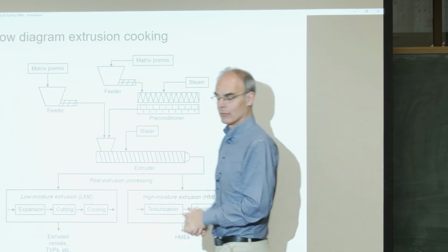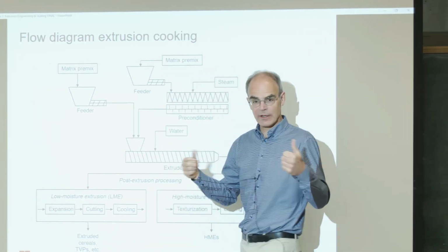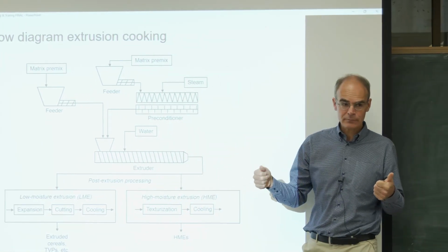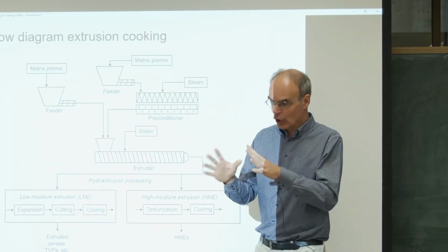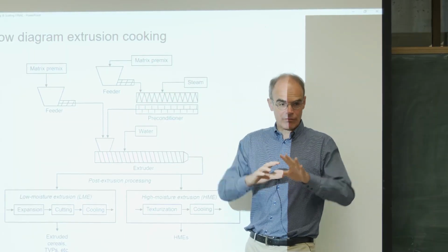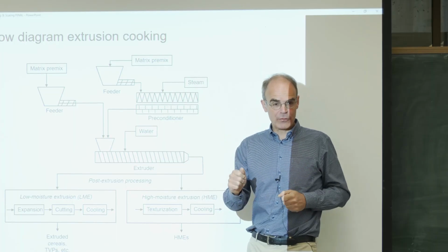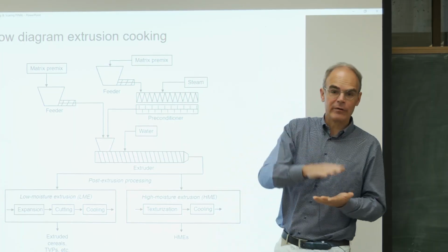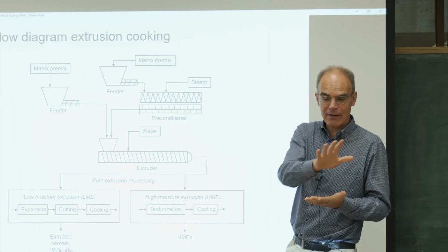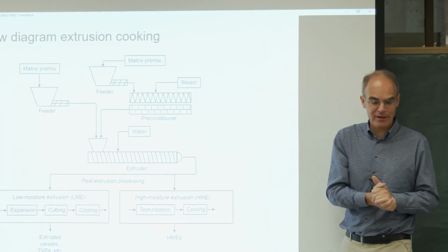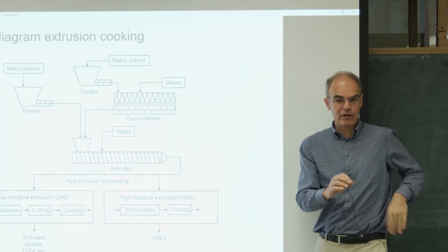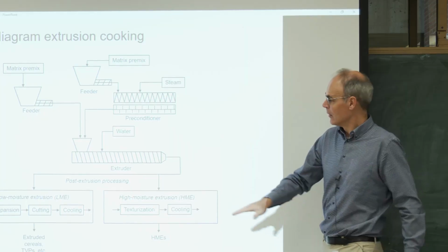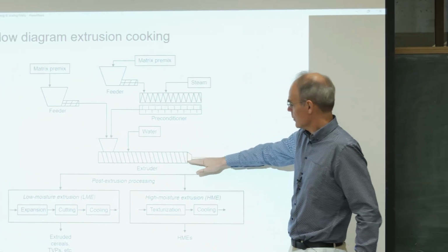Shear it, yes. We heat it, we first transport it, we heat it up further. And if the material is sufficiently cooked, so fully gelatinized or fully denatured or softened in case of proteins, we shear it. So we'll have some special elements in the screw, but we'll have a look at the screw design to see how we can most effectively shear it.